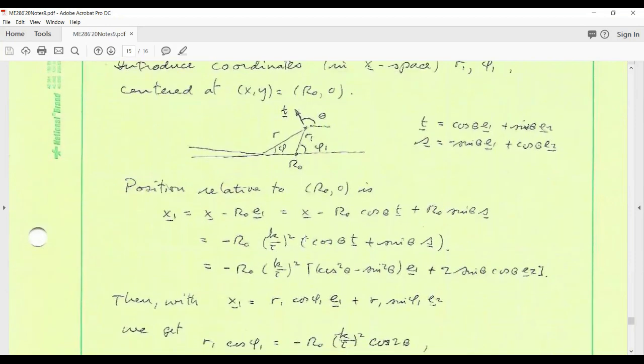If you look at the result for x that we wrote down, this Hutchinson-McClintock solution for x, and form this combination, you'll get this. Tau, again, is radius in stress space. You could reinterpret this in E1, E2 basis by writing T and S in this way, and you'll get this.